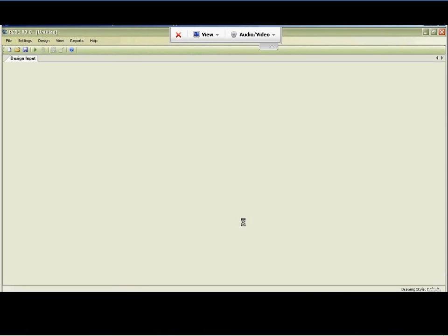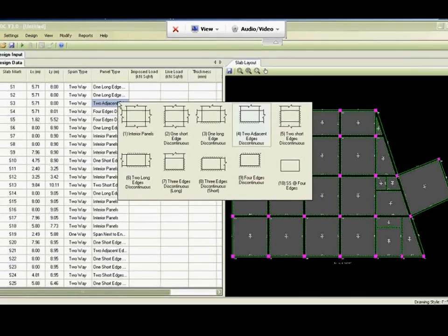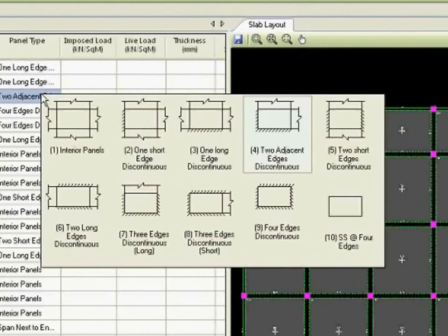Here, whether you model or not, the slabs are identified from the beam column geometry. So the software will identify the slabs. Here, as you can see, we have not modeled anything in ETABS. In STAAD, we never model slabs. It identified each small polygon, or the smallest of polygons, which could be slabs. It identifies its size, and based on the aspect ratio, the span type, and based on the actual continuum around it, the panel type.